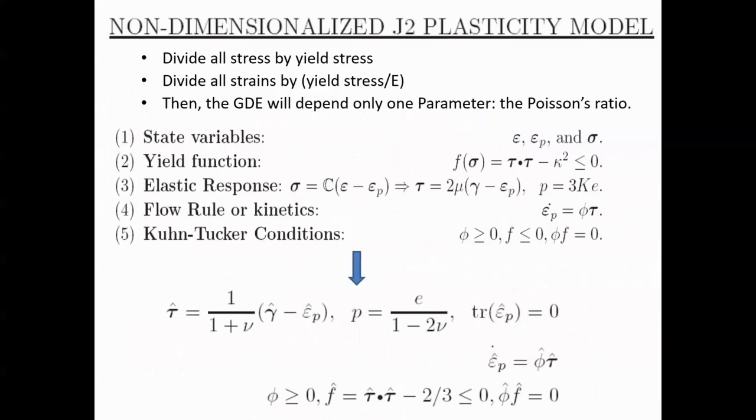Okay? Often it is possible to non-dimensionalize this plasticity model so that you can take advantage of a more general situation. If you have done fluid mechanics, this is very commonly done. So in this case, supposing I take this entire set of equations, divide all the stress quantities by the corresponding yield stress, and all the strain quantities by yield stress by E, then I'll get something like this.